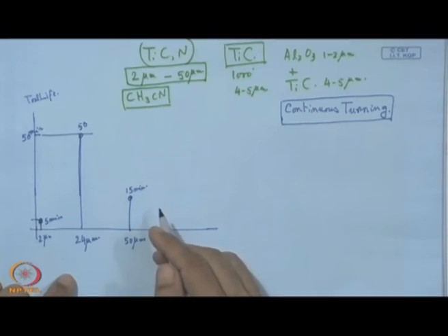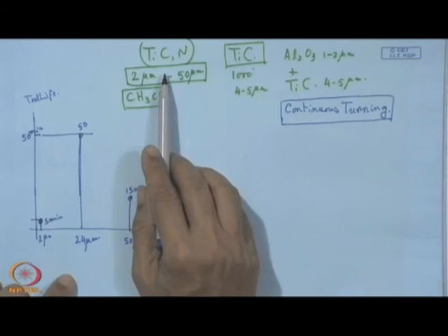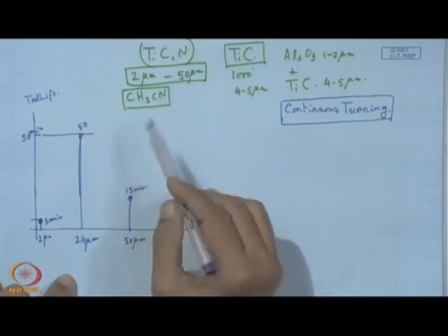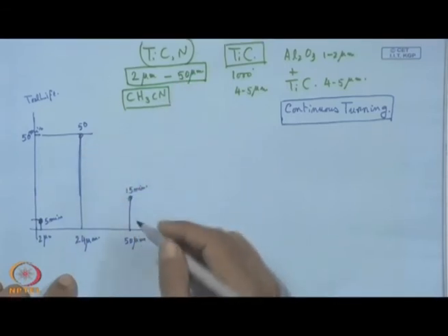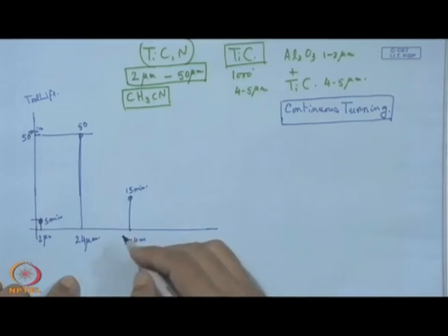So, we also find here that even in this coating, which is deposited in the range of 600 degrees centigrade, if we increase the thickness of the coating, we have premature wear on the coating, delamination of the coating.